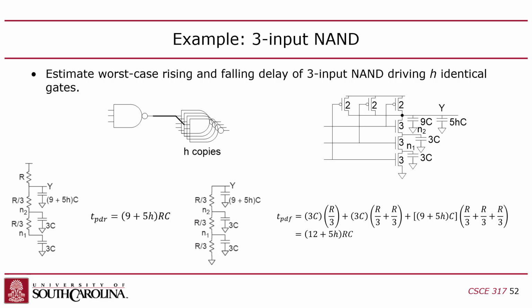Well, basically, you have to add up the source capacitors of those 3 pull-up gates, right? The diffusion capacitance. So that's going to be 2C, 2C, 2C. Those are 3 parallel capacitors, all with K equals 2. So that's going to be 6C. So I've got 6 units of capacitance for those source terminals, right? Okay?